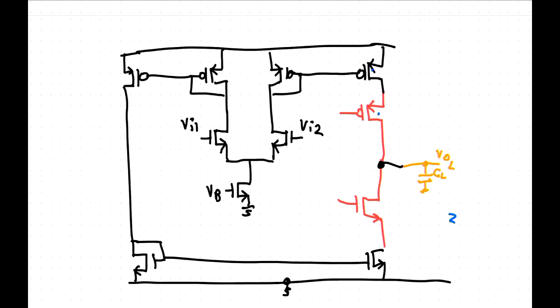So if you go back and think about the current mirrors, the cascodes that we looked at last time, we can actually make the cascode even better than what we have here with a constant gate bias, because we can pop in an amplifier around that structure. So putting in the B1 here and another amplifier up here, minus plus, the B2.